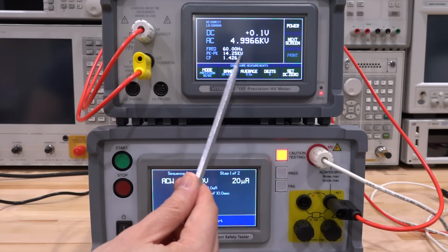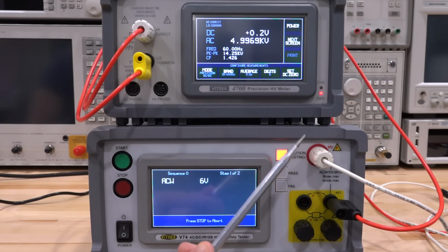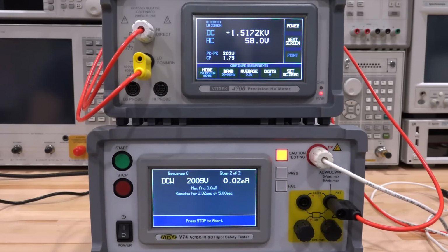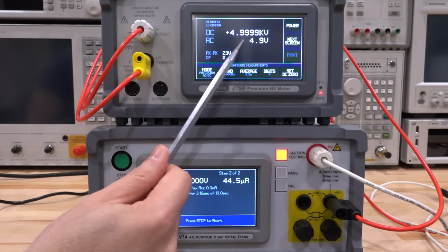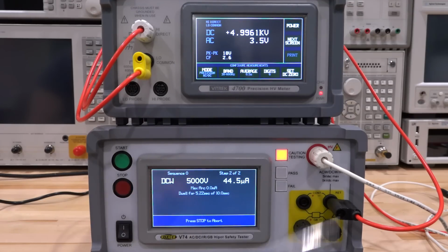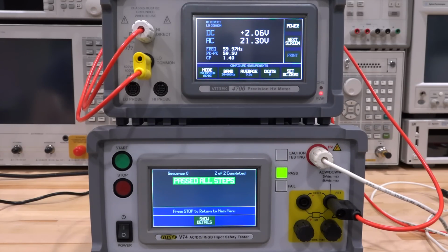And the frequency is fixed at 60 Hertz. That should tell us something about the architecture. The crest factor was 1.4 and 14 kilovolt peak to peak. Now it's doing DC, 5,000 volts. Look at that, it switched to DC. Exactly the same. There's no more AC now. AC is almost insignificant. Drawing some current, 44 microamp, going back into the multimeter, just like the Stanford Research power supply was doing. Look, and it says that everything passed.